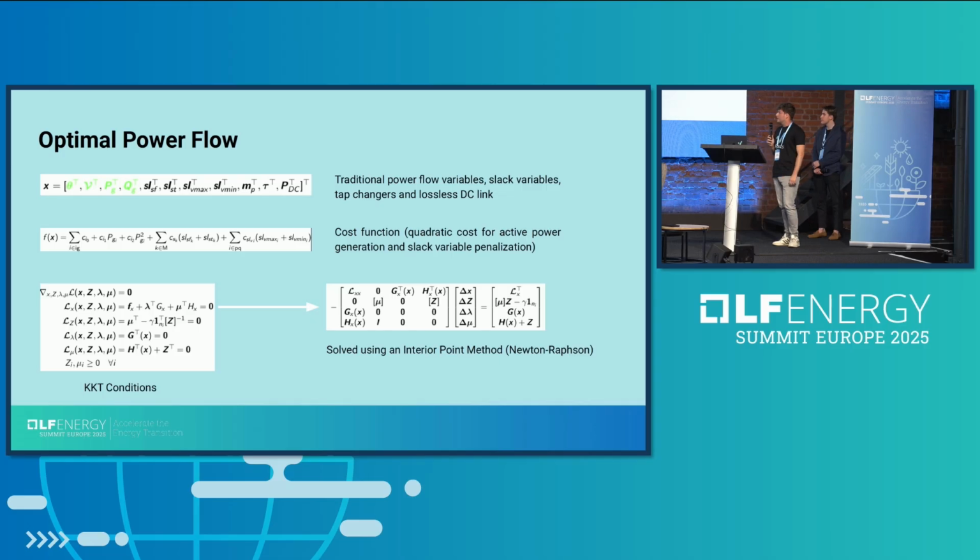We also include the module and phase of the tap of the transformers, so the controllable transformers can be optimized. It is treated as a continuous variable, even though typically these are discrete jumps. But we can get an optimal solution in the continuous field and then approximate it with the discrete jumps that we have in reality.